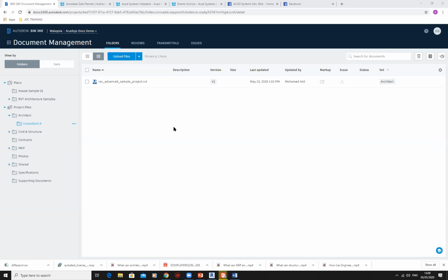So it is very helpful for Revit users, but for other software like AutoCAD or SketchUp, you may upload the models in BIM360 as well. It's still supported, but you will lose some of the special features like the 3D layer by category, because each software works differently, and so does Revit. Revit works in its own way so that BIM360 can understand it well.